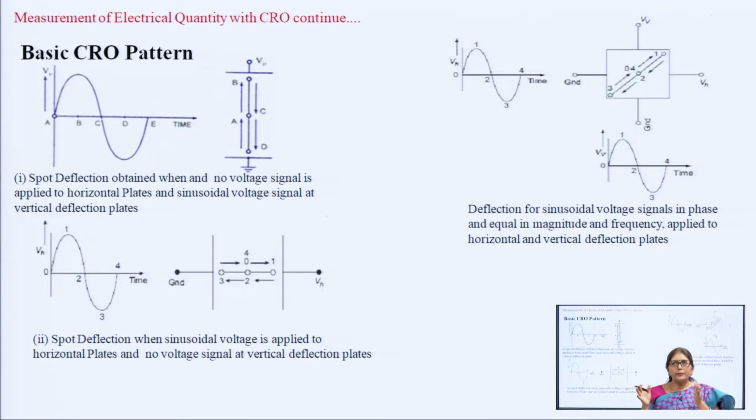Similarly, there are two parallel plates situated in the CRT, placed vertically, and they control the movement of electrons in the horizontal direction. They are placed like this and control the movement of electrons in the x direction. So, basically they control the time base signal.